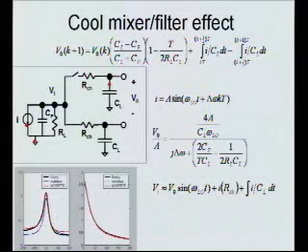So that's a cool trick for making linear low-power front ends, is you actually basically have an effective filter immediately after your LNA, suppressing wideband signals.